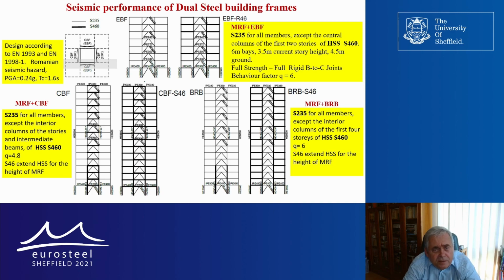We have investigated the performance of a set of dual steel building frames, realized following the previous philosophy. We have a set of eccentrically braced frames, which are multi-story frames with eight stories, in which the columns are realized in high-strength steel, 460, right?